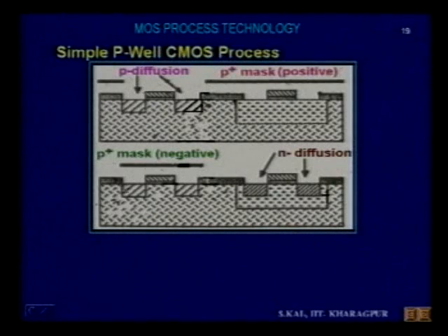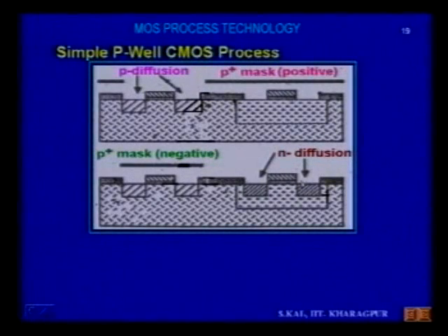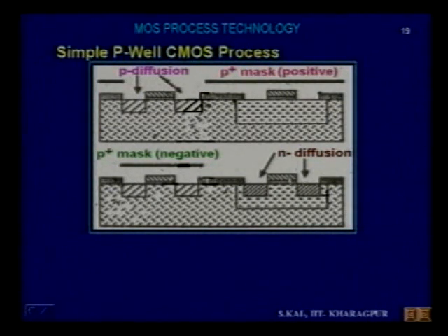So now after this P diffusion has been done, you cover this particular region using the same mask, photomasking. You cover this region and the other region you open. Diffusion in this particular region is done using phosphorus. So then you are getting the NMOS source and drain region. And since here and here are also open, N diffusion will take place here too. But the field oxide is a thick oxide, and those N-type dopants will not reach below it, into the silicon.